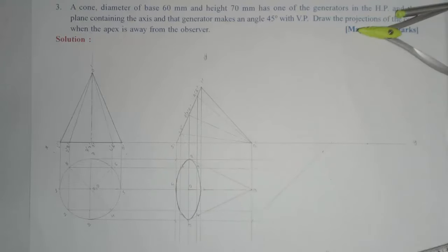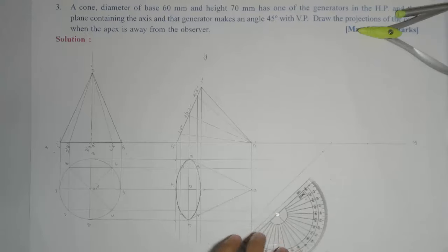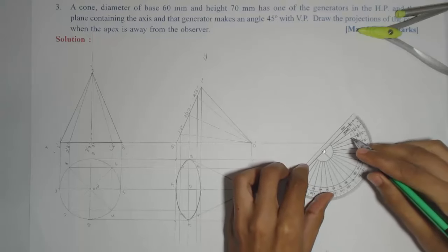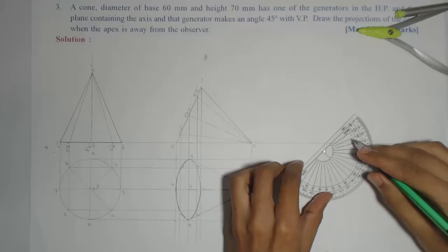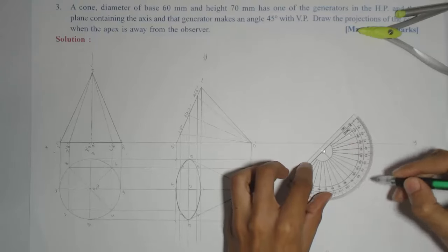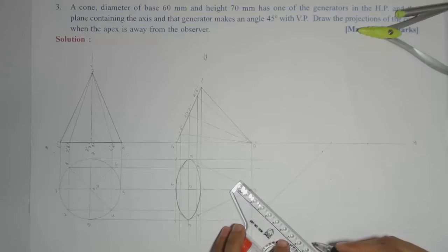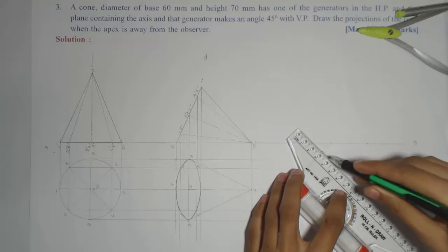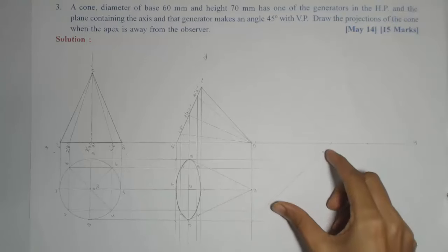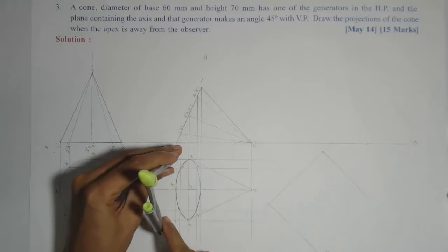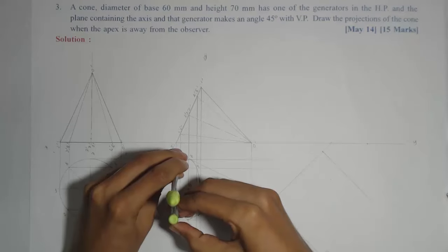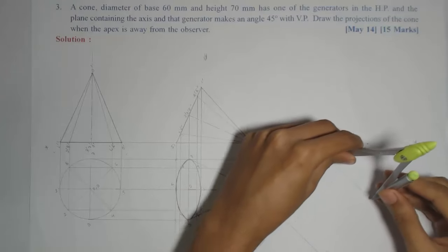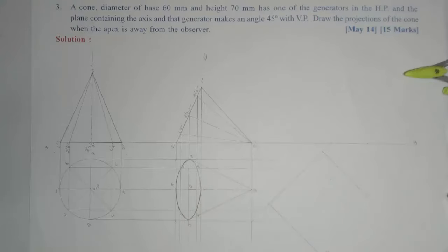Now again I'll draw two perpendiculars from each division, 90, to mark the other sides of the rectangle, then 90, and on these sides I'll mark the remaining two sides of the rectangle. Means we have already marked the length of the rectangle. Now we'll mark the width of the rectangle perpendicular to the length, which will be the same for both the lines. Okay.